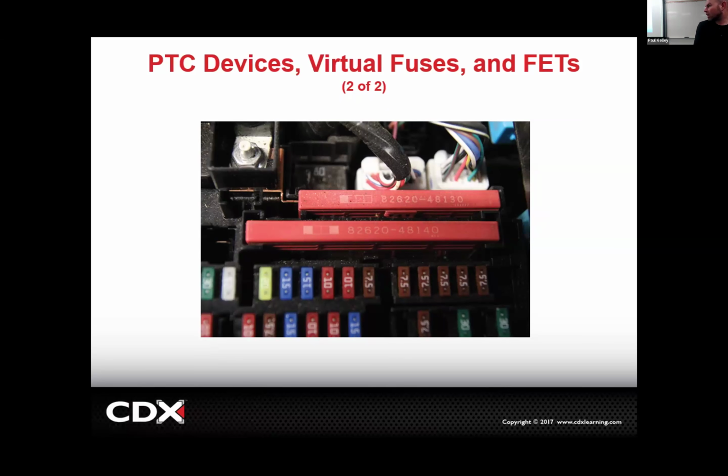So I don't personally like them for a couple of reasons. One, you can't just grab it and pull it out. A lot of times you have to disassemble this fuse box and undo bolts, and it's actually bolted in several spots. So doing the work is not really fun. And the other thing is you can't stock these. This is unique to this particular application. So the most common time you're going to see something like this is maybe one of these is for the alternator and one of them's for some other power supply.